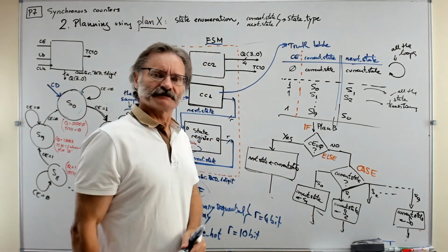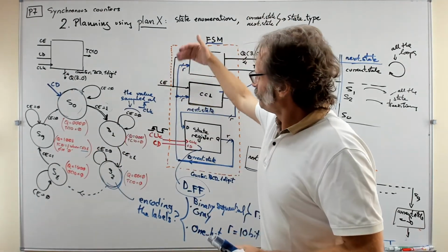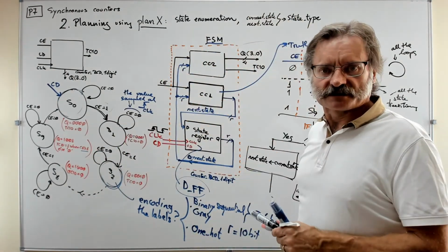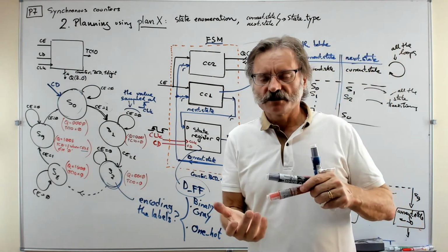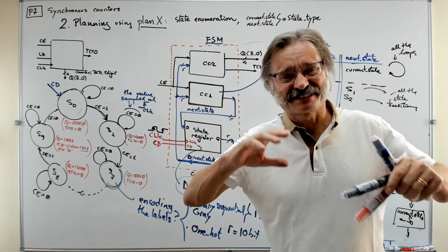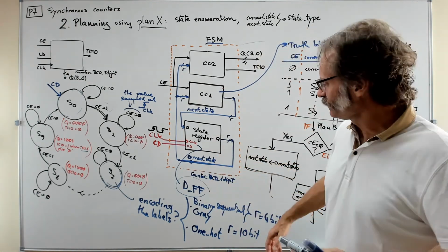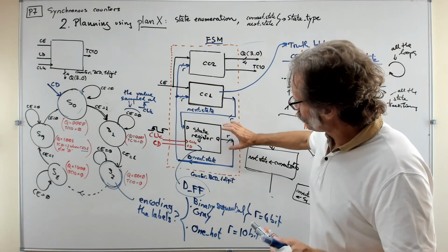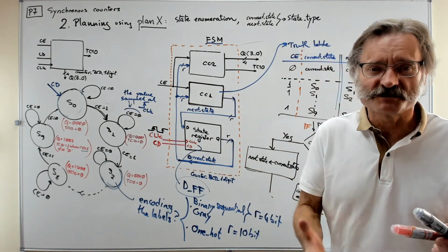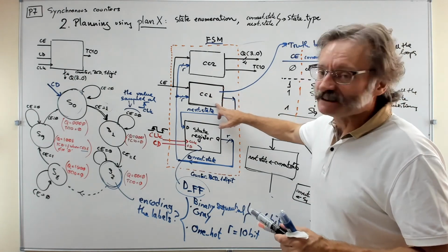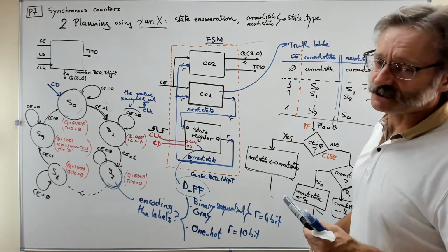So in this way you are solving the flow chart that now is immediately translated to VHDL. Alright, so you see a counter, yes, but nothing but plan X, just another finite state machine as usual. The plan Y is very similar, it's just another finite state machine, slightly different because we will not code in one hot, for example, or in gray. We will code all the time in binary, so we will have another possibility for implementing the CC1 in addition to this one that is stated here in plan X.